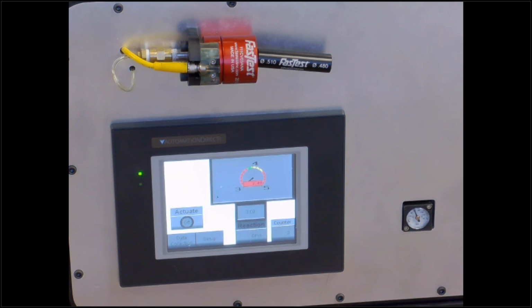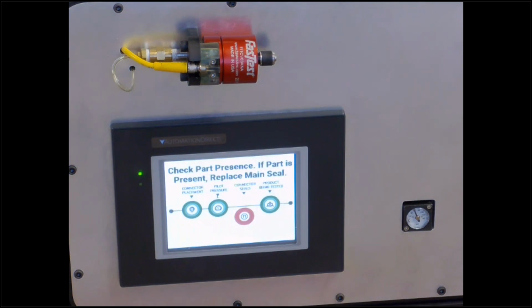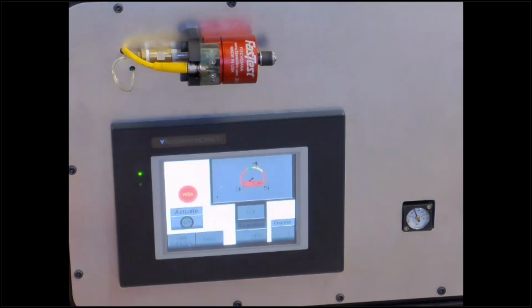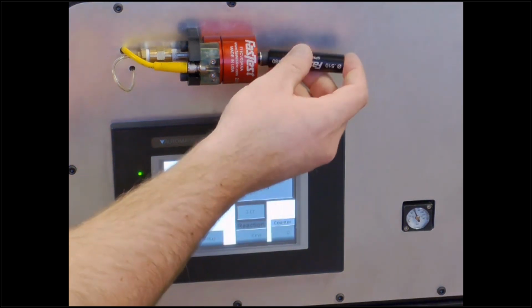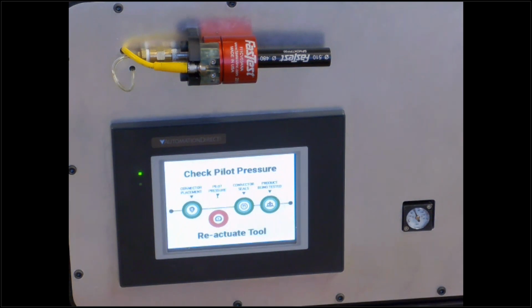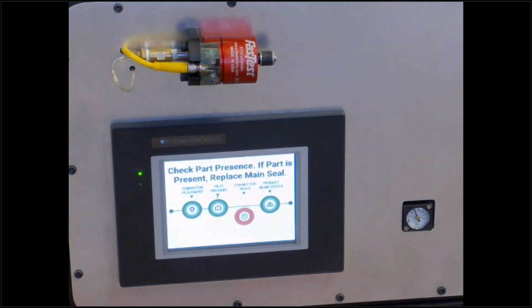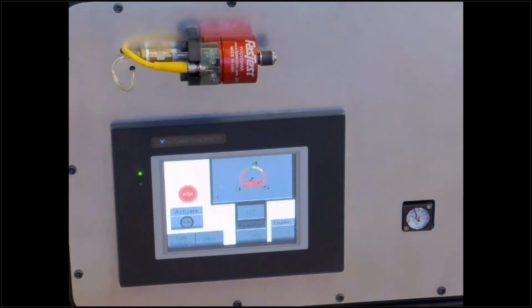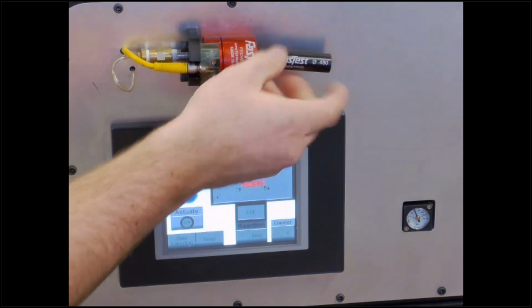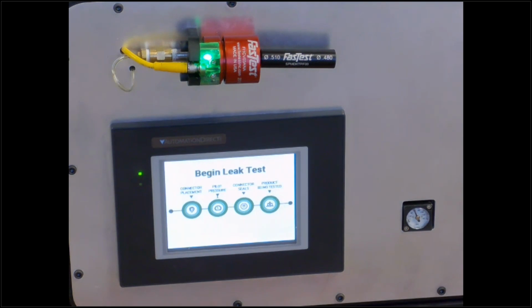So we're really excited about this technology. I hope this quick demo inspired you and gave you some different ideas on what you can use the analog output for and how it's used in a setup in a production environment. It's pretty amazing to be able to pick out whether it's under-traveled and you need to check pilot pressure, or whether a part is even in there, sensing part presence. A lot of this will help make all of your leak testing a little bit more reliable and provide you data to learn and characterize these devices over time.